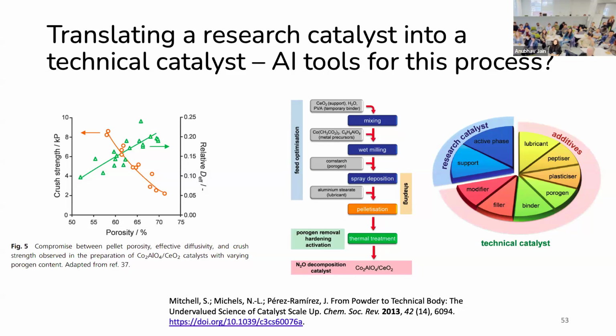You can have better catalytic activity, but your mechanical strength is going to be low. Whereas if you go the other way, then you can have high mechanical strength, but now the gas can't get into the catalyst. So you have to first do all these experiments to figure out the relationship between your porosity and these other properties, and figure out, for my downstream plant, what is going to be the best optimal trade-off for my pellets, or do I have a mixture of pellets or whatever.